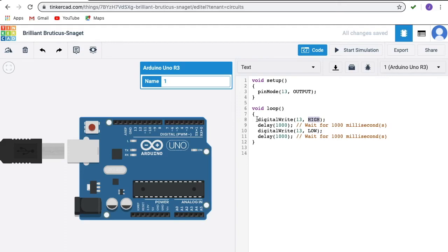Okay, after doing this, I want the LED to be turned on for 1 second. That is given over here. The value which we load here is in milliseconds. There is a function written in the library background, so we don't have to worry about calculating all the delay times. Just type delay and type how many milliseconds of delay you need and give it over here. After turning it on, it will wait for 1000 milliseconds.